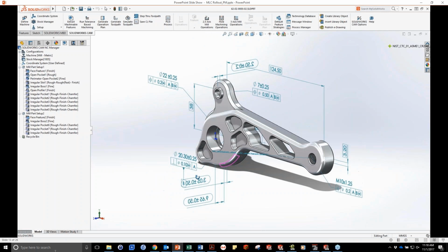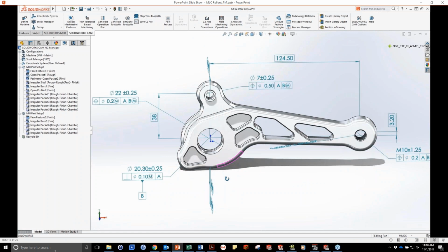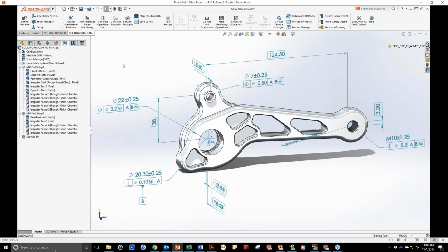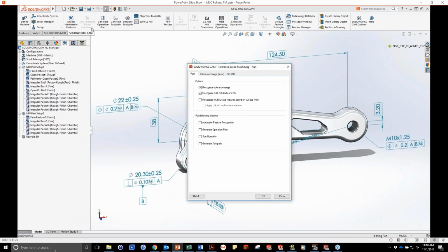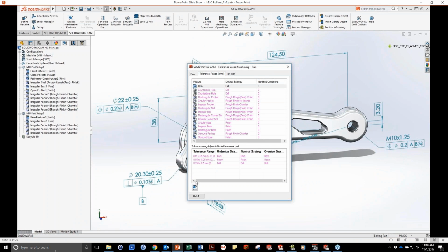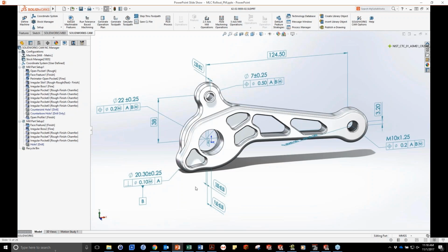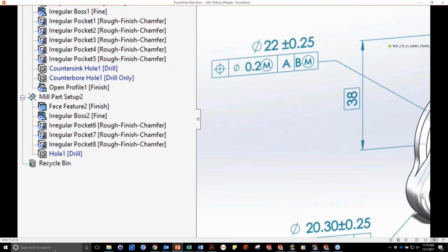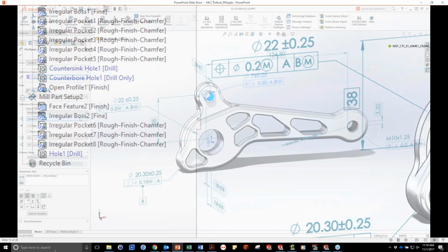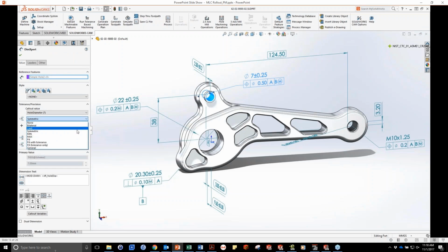In addition to your rules, your manufacturing best practices, in addition to your automatic feature recognition, this will look at those tolerancing setup and come up with a scheme and order of operations for machining. So depending on where your datums are, depending how fast or how tight you want your surface finishing to be, you might need smaller surface finish cuts. You might need to start at a different 0-0.